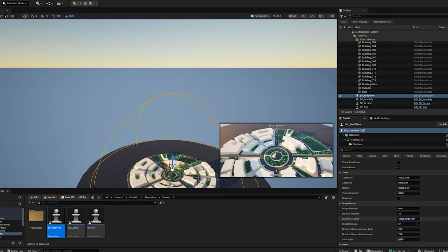Our third navigation mode brings things back to human scale. You all must have used Google Street View. That node-based logic is actually perfect for multi-platform navigation. Let's adapt that and call it POV mode. We need 2 blueprints for this, one player pawn to handle the camera controls and a second blueprint for the physical points placed in the world. The pawn can look around freely, but it can only click to move between these points.